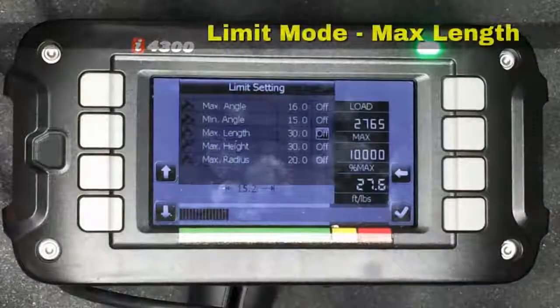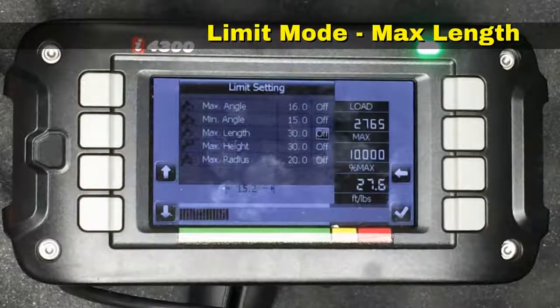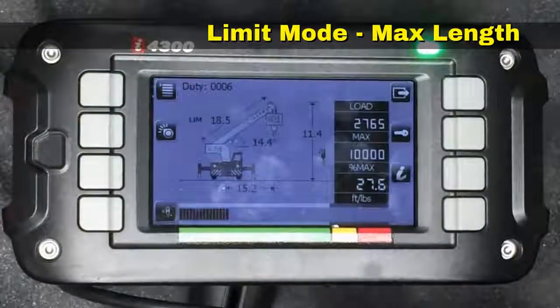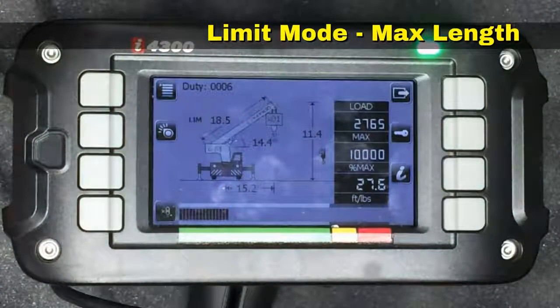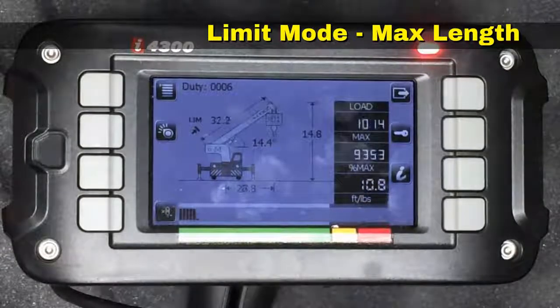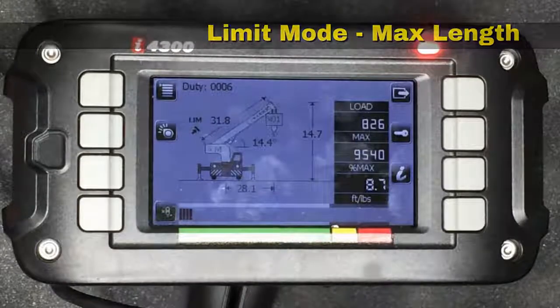Now we're going to look at the maximum length limit, which is currently set for 30 feet. Once I hit the check mark, it will turn it on. And then back on the screen, we see the LIM show up next to the boom length. And as the boom length is increased, it will eventually go into an alarm mode. Again, you see the arrow pointing towards a flat bar, indicating that we are at or past the maximum boom length.